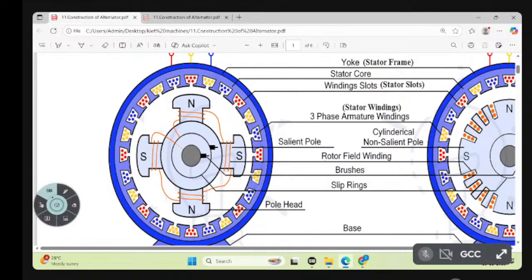So from the positive brush, the terminal comes like this, over, and then goes to the other brush. It actually has to be drawn here, but it is rotated, so it is drawn like this. Make a note: this is a positive brush, this is a negative brush. That is enough. Now the rotor consists of simple poles and rotor winding. So that is the construction of the alternator.